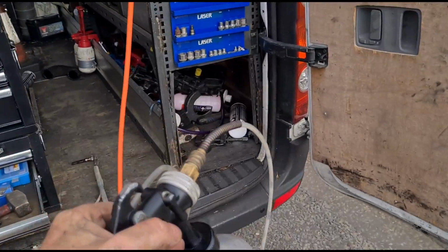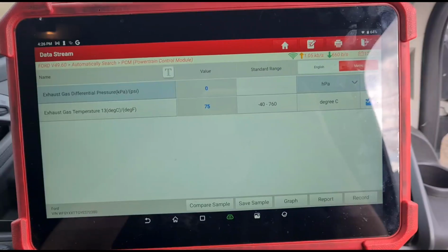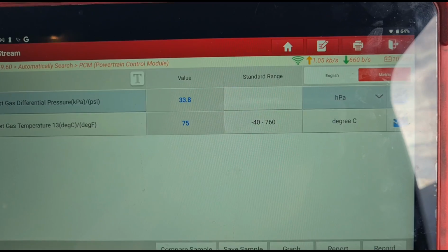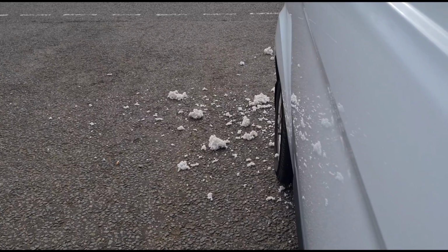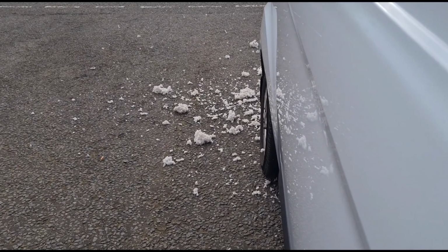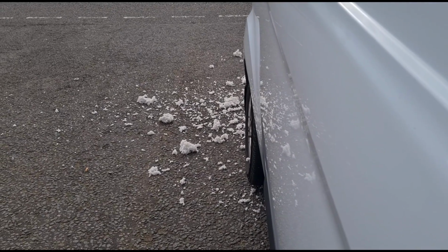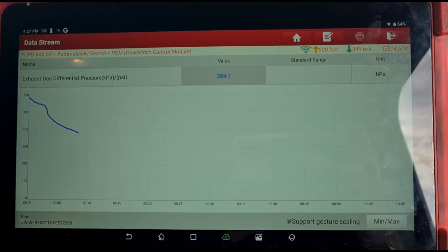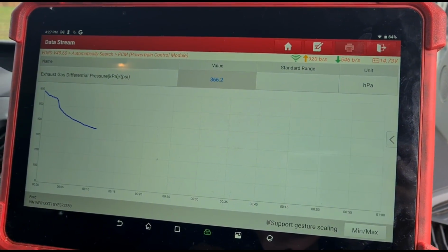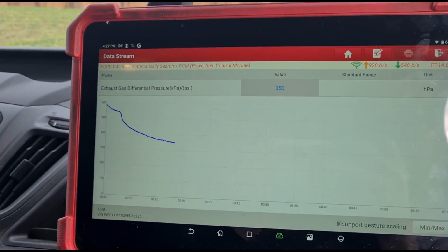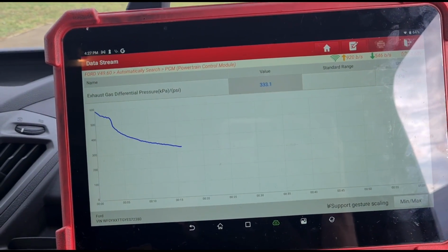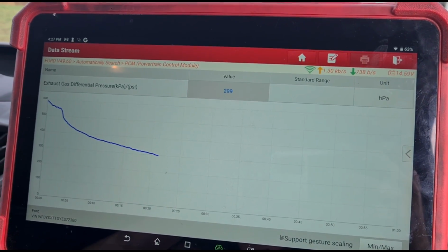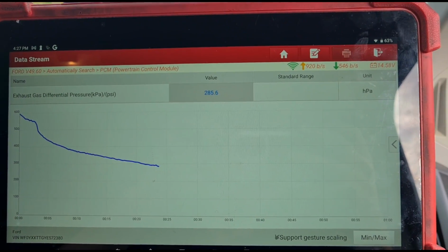Okay, so that's all of the fluid gone in. That's the compressor up there. Now we're back in at the van. We're going to start it back up again. We're going to give it a few revs. And we're holding the pressure there, holding the revs on it. Just going to see how low we can get that pressure. We want to see it ideally around 50-60 millibars.